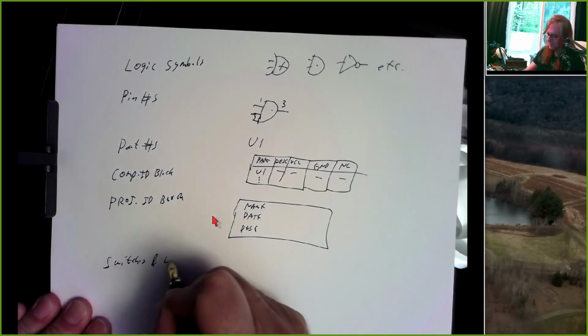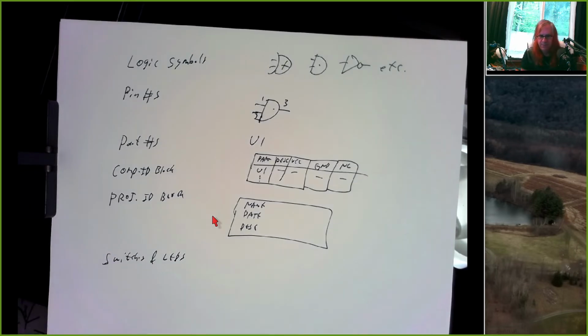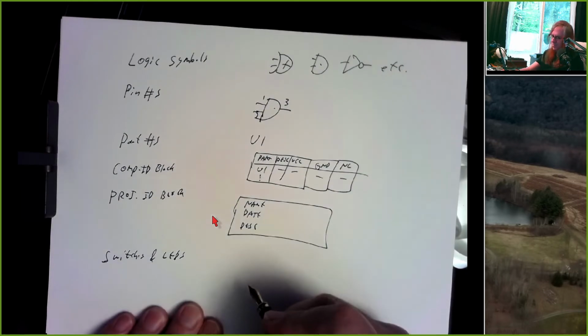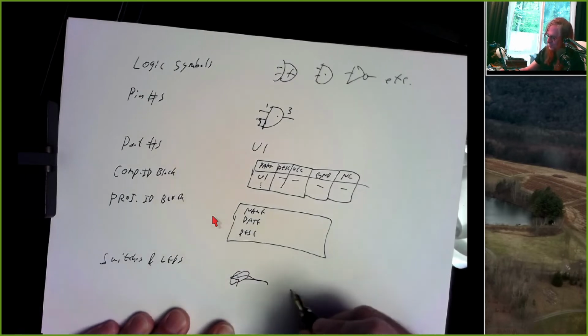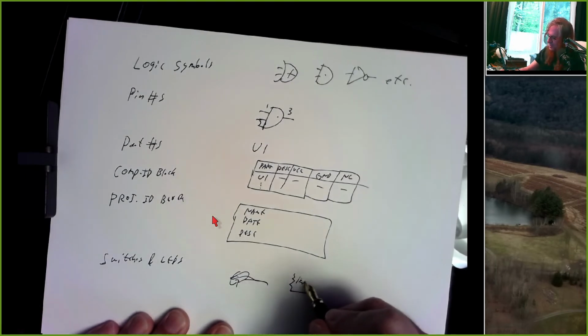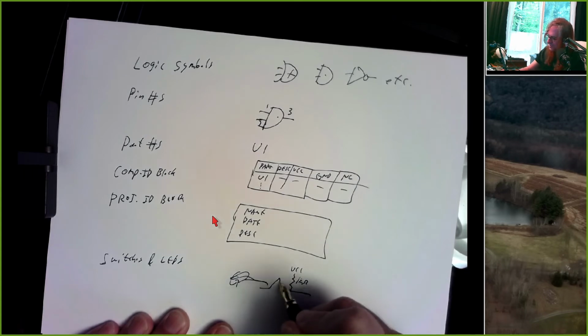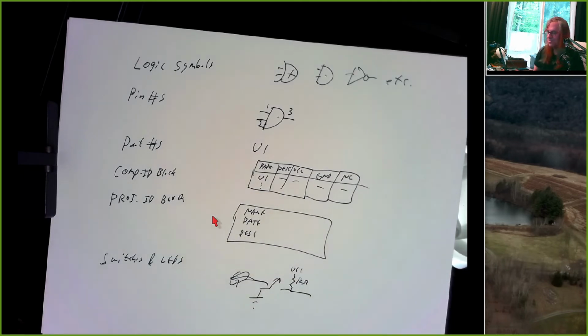Switches and LEDs. This is a wiring diagram. This is something you hand to somebody and they build your circuit for you. So having something like this going into your circuit, well, there's no component called G, right? And you can't take this and change the value of the input by doing something to the letter G, right? So you take your input and you run it through a 1K resistor to 5 volts and you have a switch and this goes to ground. There's an input.